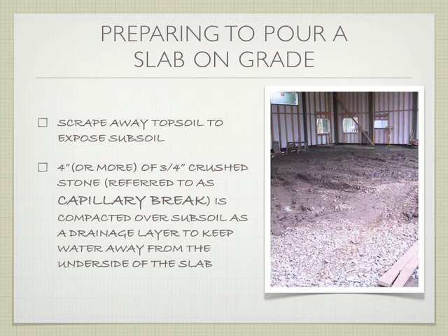And that's the big risk in a slab on grade, is that the moisture could come. Certainly, if you have a crack in the floor, the moisture could come right through that crack. And it's something you have to be really careful of. Now, of course, there are mitigating ways of dealing with it. So I ended up coating the floors with this epoxy resin that seals off the top of the concrete so that you can then put carpet down and it won't come through.